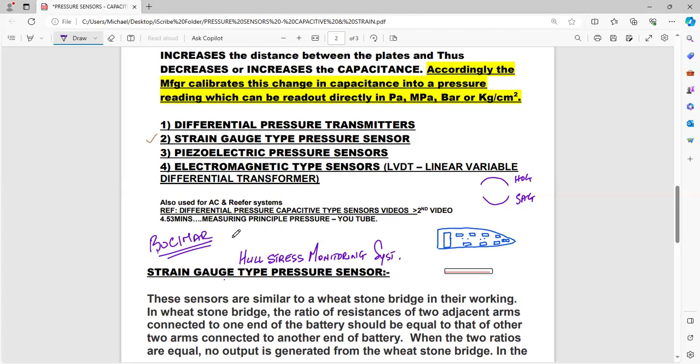What would have happened is possibly, and they didn't have this system on board, okay, it was long ago, they didn't have this hull stress monitor on board. So possibly when the chief officer loaded, he had loaded the ship incorrectly, where the ship was stressed too much.